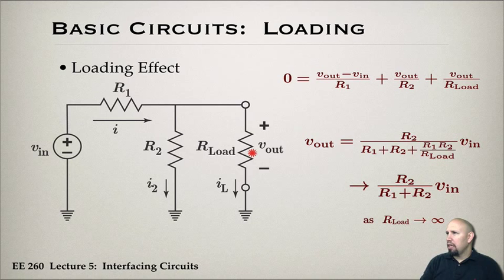So that's something to keep in mind. That's called the loading effect. That is, when you tack something onto a circuit, it tends to drop down the voltage that you're working with. In some cases, that may be severe. In other cases, it's not a big deal.